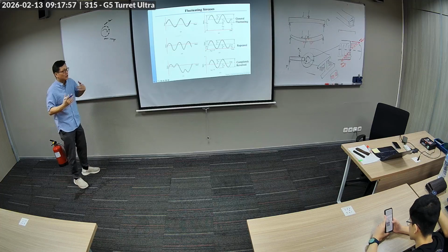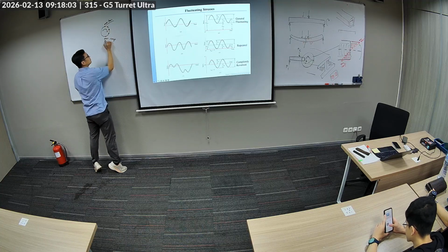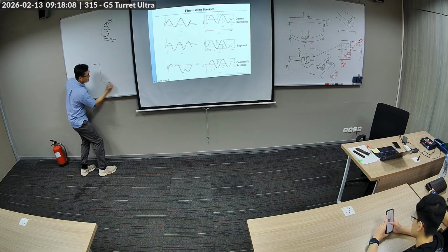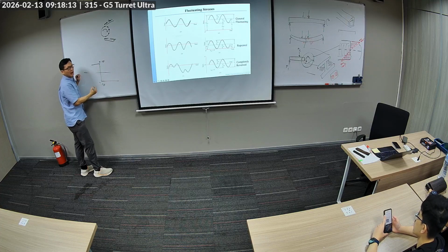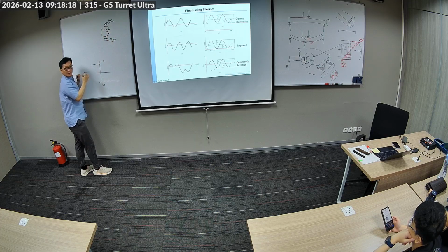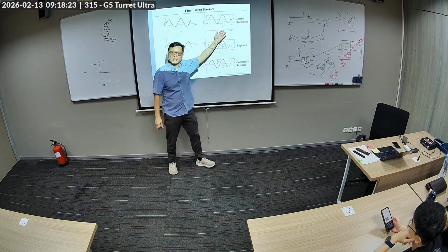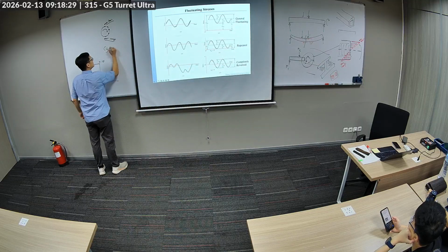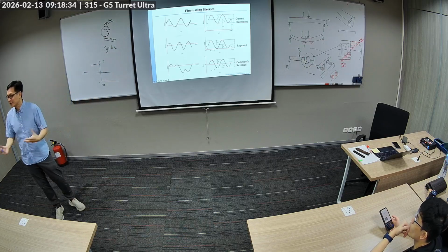So the stress I'm experiencing is going from maximum tension to maximum compression, but I'm not jumping from maximum tension to maximum compression, like positive 10 to negative 10. I'm gradually experiencing that fluctuation. And so what is happening? It's called a cyclic stress. Cyclic stress means it's cycling.